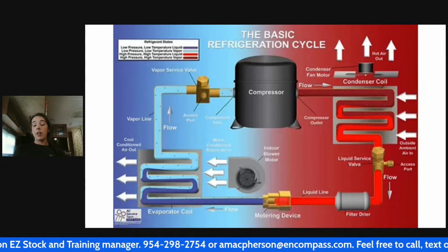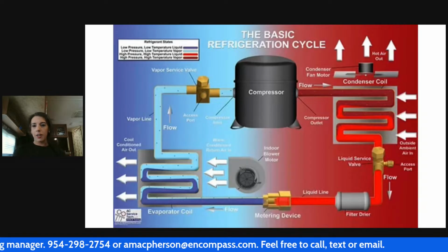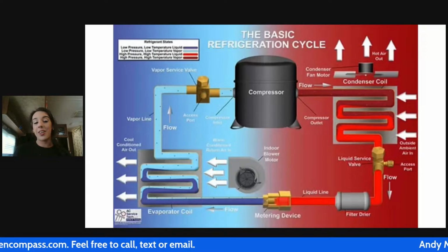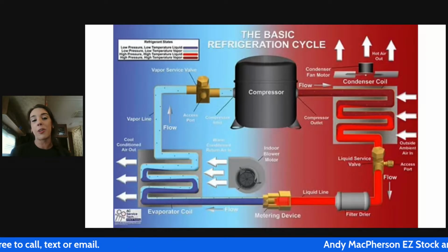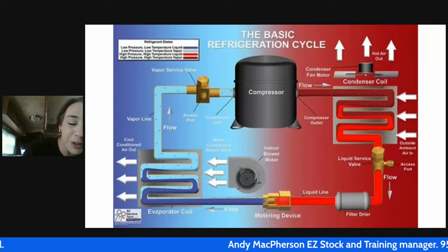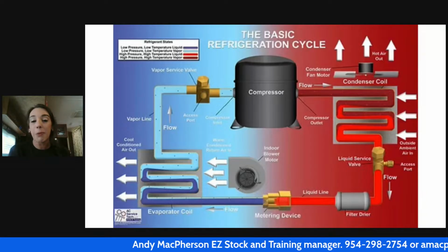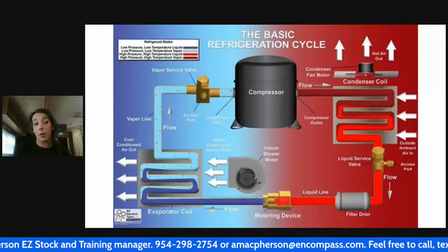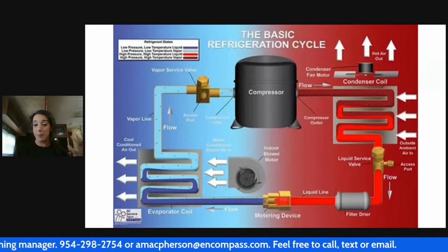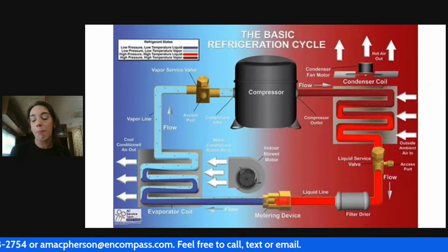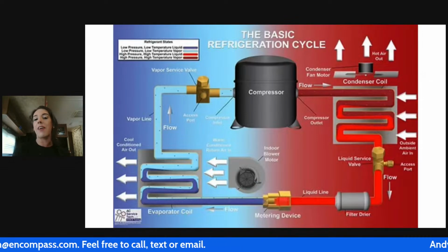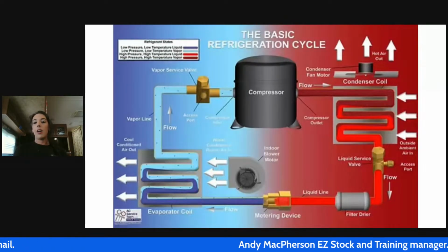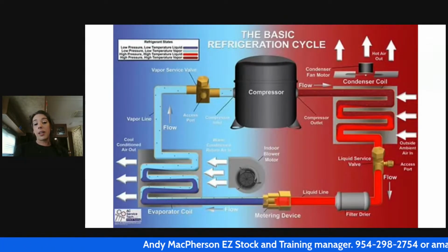The other thing is you could show up and have all these crazy weird temperatures and be like, what is going on here? And I actually did this the other day. I got such tunnel vision on a unit that somebody sent me a picture of, and I didn't even look at the pressures because I'm so used to the pressures not mattering to me. I'm so used to it being a diagnosis that I need temperatures for. So I didn't look at the pressures. And if I had, I would have realized that they were 128 and 158. They were pretty much equalized, which means my compressor was not working. My compressor was junk. I could have told that in 5 seconds if I had looked at every piece of the puzzle instead of just the ones that I'm used to looking at. So we really want to make sure we're taking all those puzzle pieces and putting them together.